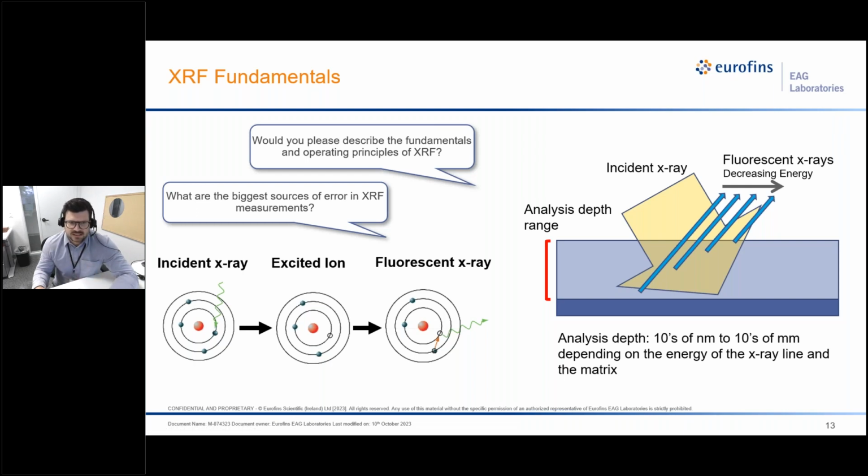Since this is a lower energy position, the excess energy is emitted in the form of secondary fluorescence X-rays, and each element has a specific energy it emits, which is how we determine what elements are present in the sample. Since the X-ray secondary fluorescence intensities for each element correlate directly to the number of atoms present, we can then determine the concentrations of all those elements.